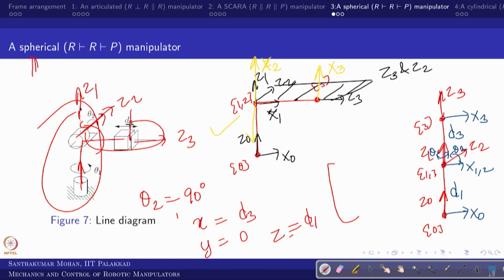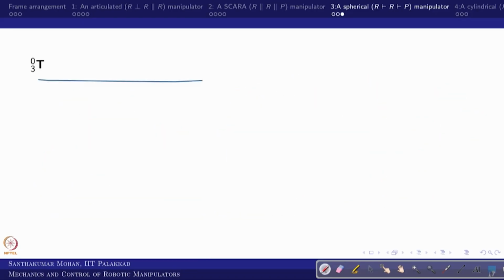This is what we put as x3. In the sense x3 is on the z0, so 0 0 1, okay. The second one is coming back. So, what would this be? This is what y3 comes here, but here this is opposite, so 0 minus 1 0. The third one is 1 0 0, right. So, we will cross check that it is obtainable here.